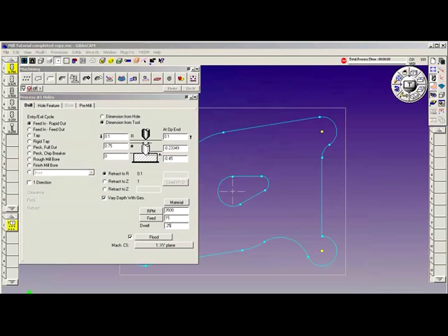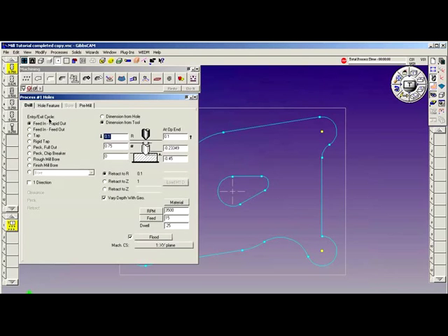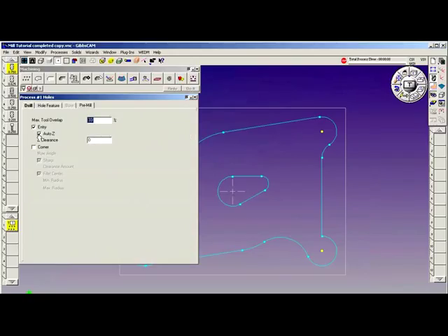All right, so we've got that tool properly defined in the drill page or tab. Next, we go to the pre-mill tab. In the pre-mill tab, I have entry hole with auto Z selected. This means that it's going to drill an entry hole and base the Z value here and give me the option of using a clearance. I can stay away from that value if I wanted to with a clearance. If I wanted to drill out the corners, I could select the corner and give myself drilled holes in all the corners. We might come back and do this.